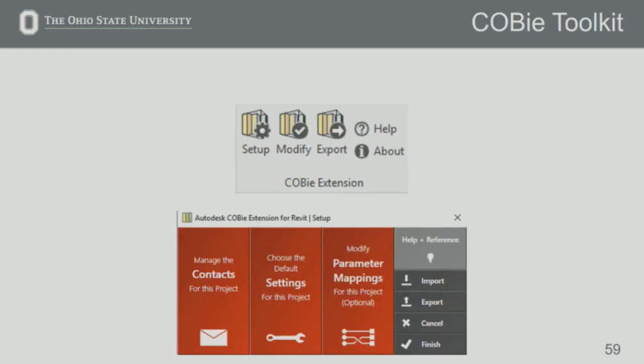I just wanted to give a quick plug also that we use the COBie Toolkit, which is part of the tools that the TG already mentioned. We found that this, for us, is the best way to get the data initially out of the model. We actually have the AE, towards the end of the project, export out a COBie spreadsheet of all the data for all the models, and then we take it and run a macro on it to make it a very simple spreadsheet, because COBie, as most of you may be aware, is very complex. It's hard to work with.